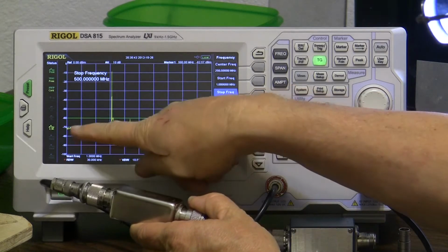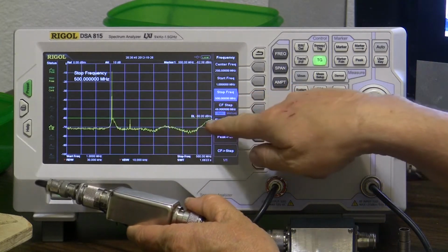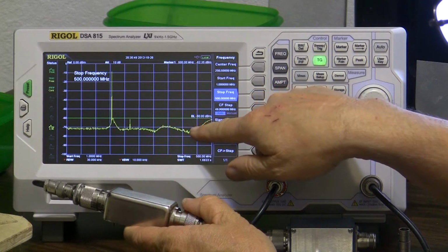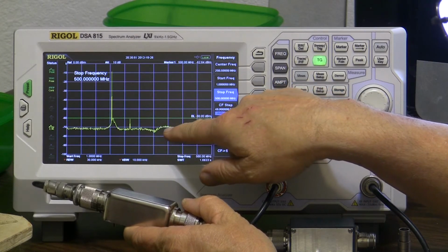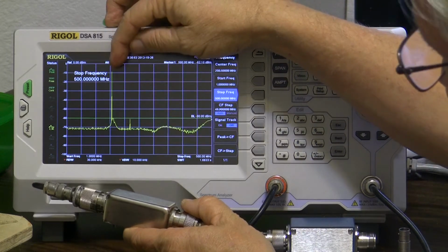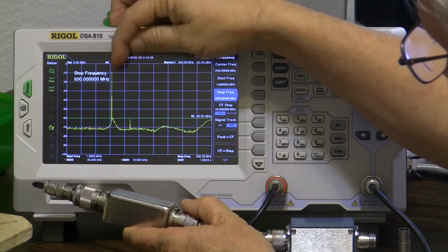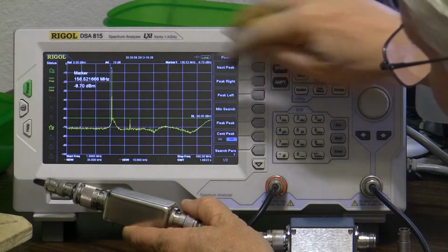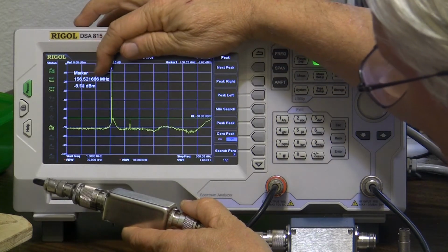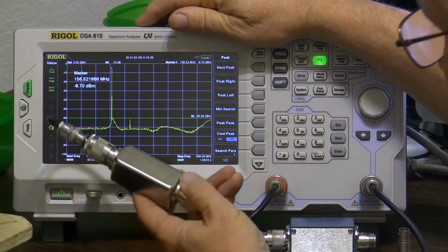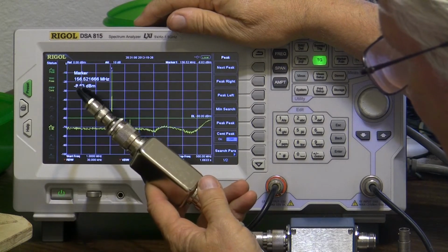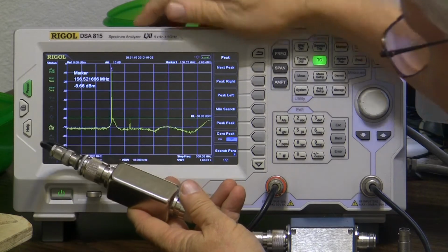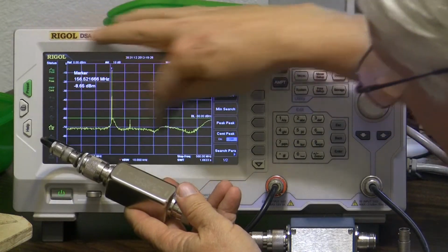Now we see that the ultimate is about minus 72 dBm, something like that. And we have some loss at the top here. It's actually showing a little more loss than is actually there, I think. Let's hit the peak. It says it's 156.521, which is not quite the frequency that's here. This is 156.125, actually 157.125. But remember, we're sweeping a long distance here.